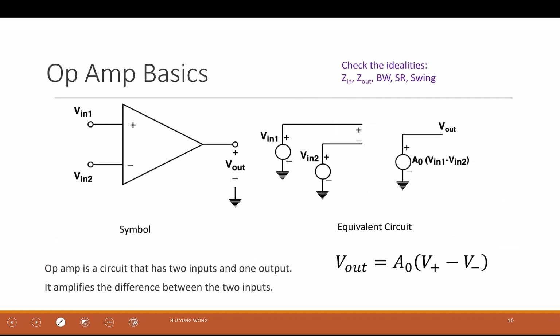So we just said that. So let's look at this circuit. This is what you just drew, the operational amplifier. I have 2 inputs and 1 output. Although I call them V in 1, V in 2, it doesn't matter, right? And indeed, my equation here should be changed to V in 1 minus V in 2, because V in 1 is connected to the plus, and V in 2 is connected to the minus. Is this okay?